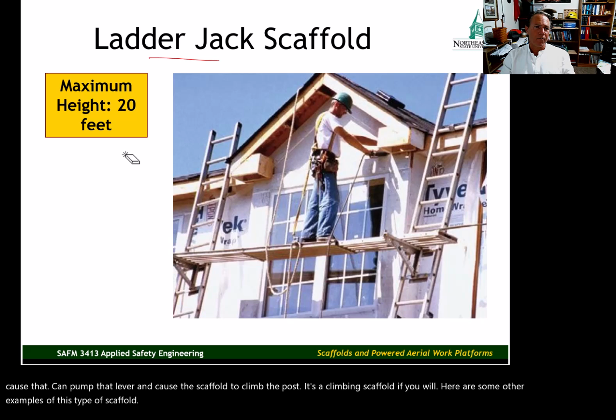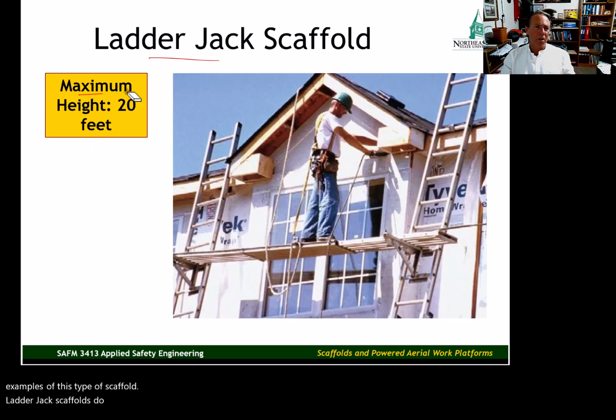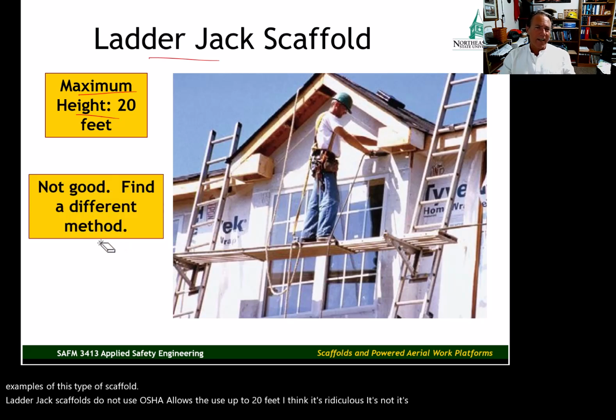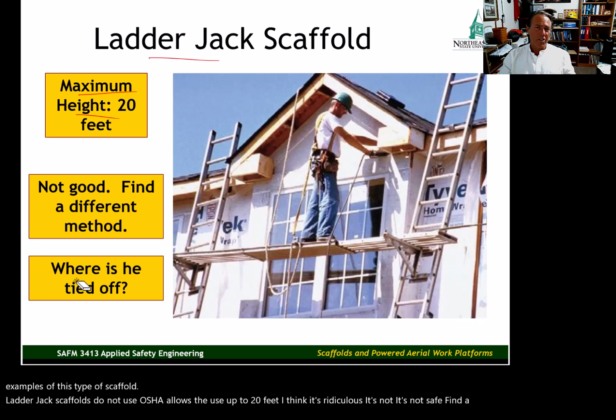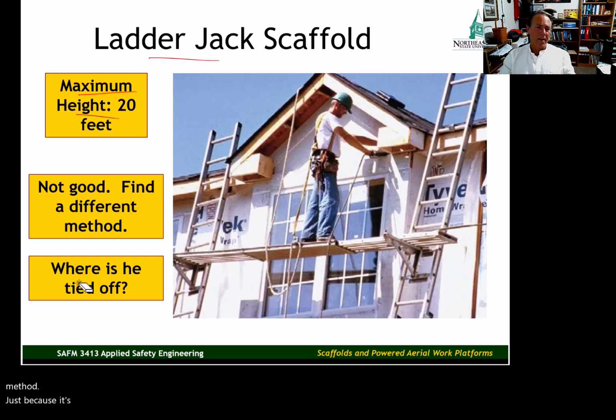Ladder jack scaffolds, do not use. OSHA allows the use up to 20 feet. I think it's ridiculous. It's not safe. Find a different method. Just because it's legal doesn't mean it's safe.